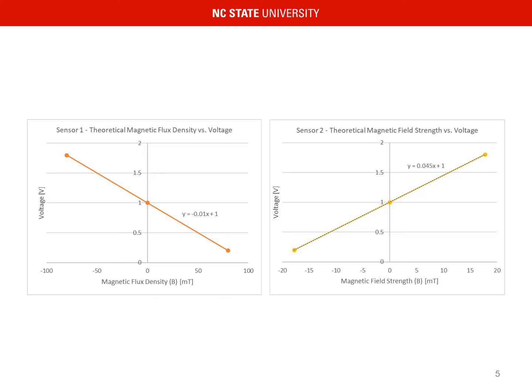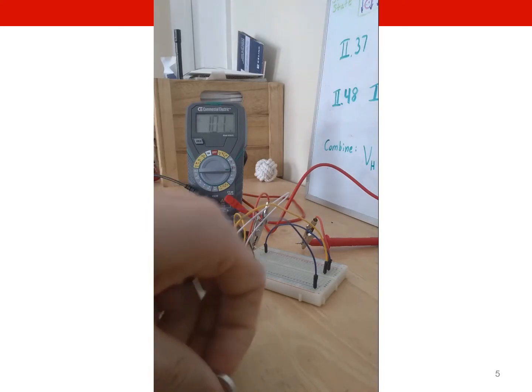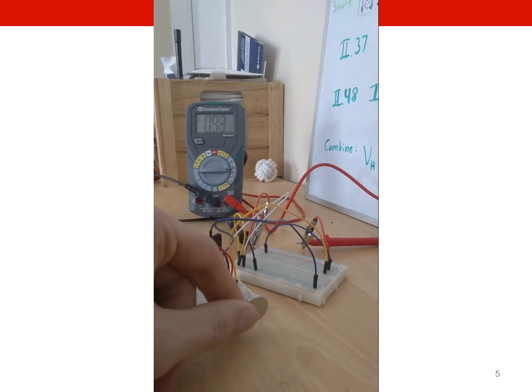You can see the sensitivity levels of the sensors as the slope of each line. Negative versus positive sensitivities dictate the response of the sensor to different magnetic poles. Here's a Series 5053 Hall effect sensor in action. The output voltage will increase or decrease in the presence of the magnet until the field saturates the sensor. The magnetic flux density that causes saturation depends upon the sensitivity level of the sensor.